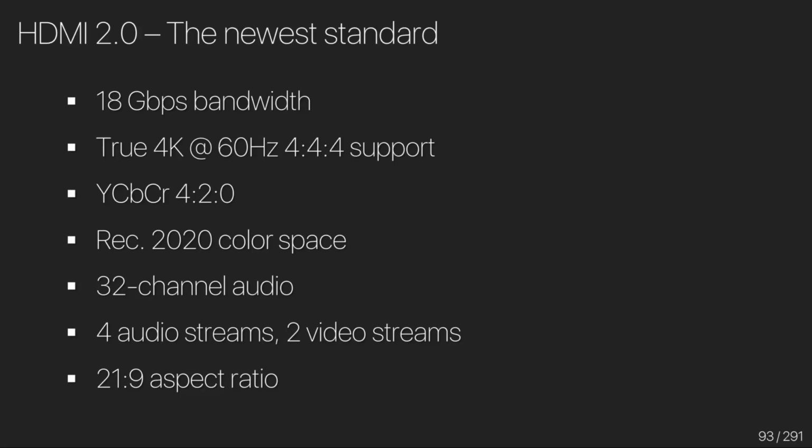How to handle EDID when dealing with SDI or 3G SDI signals? I don't have as much experience with SDI, but from my understanding, you set your source and your display device to a pre-configured broadcast standard, and it interprets the signal that way. So in that sense, the source device isn't actually reading anything about the capabilities of the display device. You have to manually set that, and use the SMPTE standards, which can be a drawback, but it can also be one of the strengths because the standards are very tightly defined, and you should know exactly what you're going to receive at the other end. Yeah, SDI is bulletproof. HDMI and DVI are flexible. That's a good way of putting it.